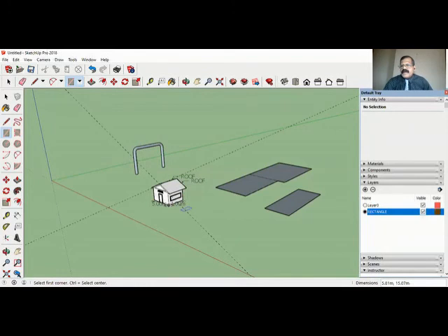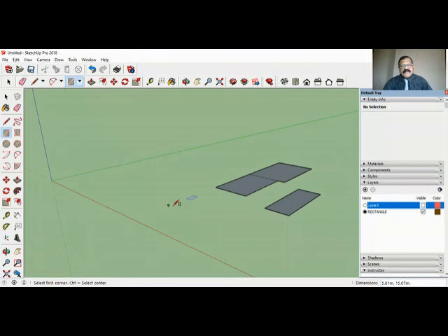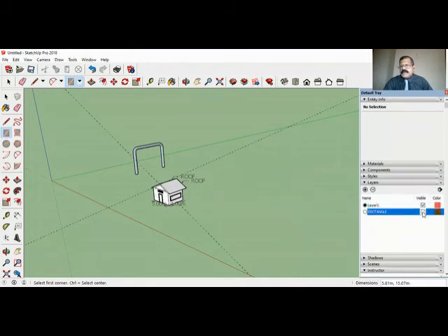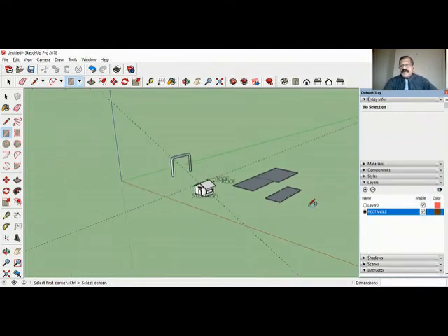All other things came in the zero layer. So if I remove the tick, all other things will go. If I want to make this invisible, this is the current layer, you cannot make it invisible. So go to the zero layer and remove this. So you can make it invisible. So you can use the layer command also. It's a very powerful feature. Whenever you make new things, you can make them in layers, so anytime you can make them invisible. Okay, so that's a very interesting command.